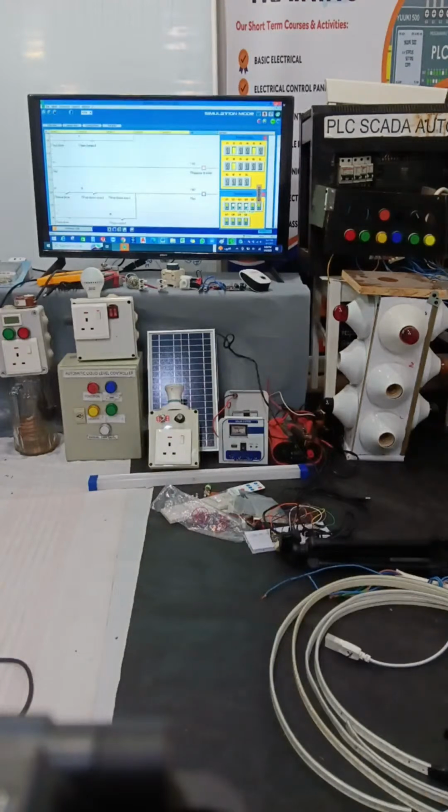Now still we need 20 kVA. So what will we do? This controller gives 20 kVA. Now this is the 10, 15, 20. 10 plus 15, 25, plus 20, 45. Then you still need 25. So this will close. Now all capacitors, 10, 15, 20 and 25 are on.